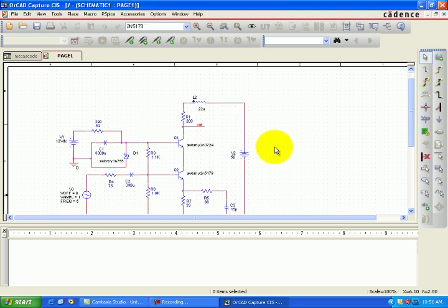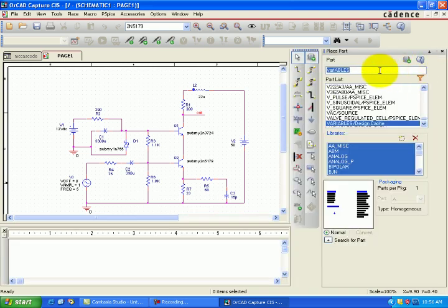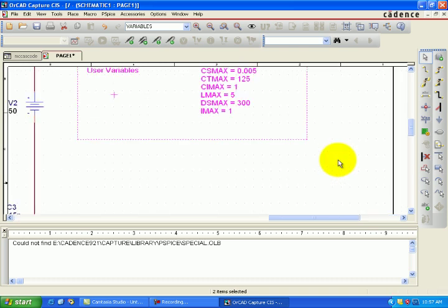The steps in the Monte Carlo are just assigning the tolerance to the model parameters and configuring the AC or DC profile. Now apply the test measurement functions and then run the Monte Carlo. The parameters are all the variables in our circuit profile.